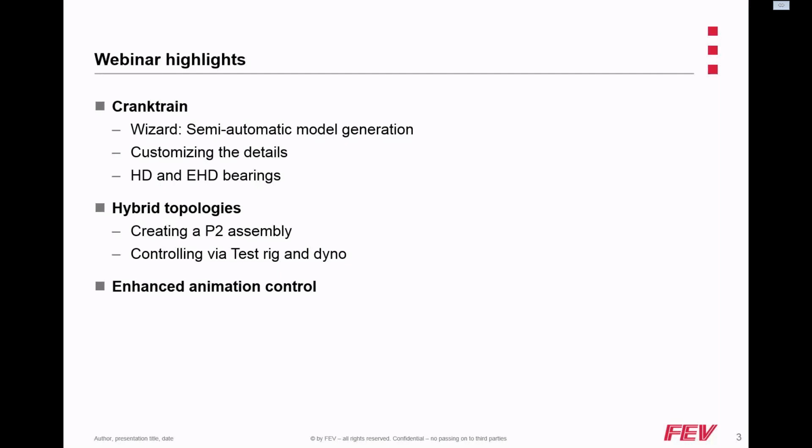The second one is, does the general contact gear need external geometry? I do not know how to answer the question because the answer is yes and no. Till Virtual Dynamics 2019.2, our latest release, you needed an external geometry to use this general gear contact, the highest fidelity. But we have worked on that. In the upcoming release, or in the next few weeks, the general contact gear will be able to work with internal geometries. We have also done internal comparisons and investigations, and it looks quite promising, which means you should be able to use this highest fidelity model without even having a CAD data file. You would not have to go through this entire process. I hope this answers the question.